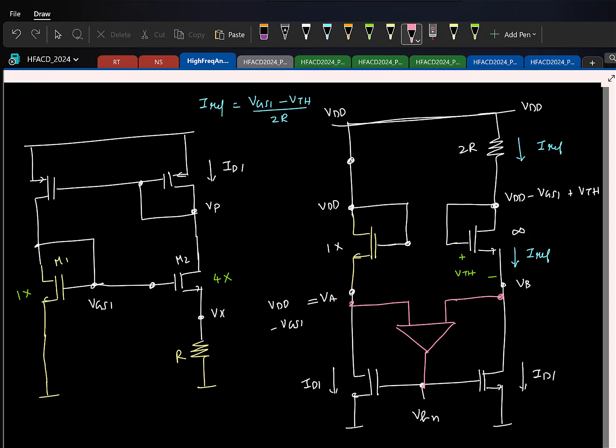So what do you think will be the signs? Which side will be plus? Right side, because if this current is greater than ID, I have to increase ID, which means this voltage has to increase. So I basically have to follow this. So this will be plus and minus. Once again, by working out the loop gains, you can prove that this is still in negative feedback.